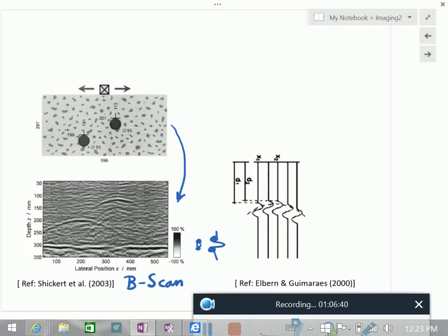But from this, you would know that something is blocking the path of energy from the transducer downward. This is actually a method that people use also in industrial NDE to find very thin delaminations inside nuclear power plants. This is just pulse echo, so you're just taking a transducer and then you move it. Absolutely, this is all related to the same kind of experiments, pulse echo.